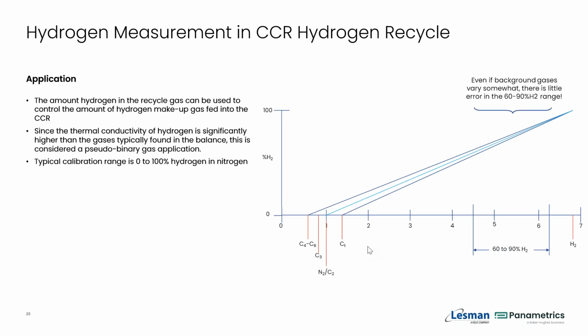In a CCR unit, there's hydrogen being fed in. There is your feedstock coming in, and then you have your product coming out. But in order for the reaction to go to completion, you do not typically use stoichiometric amounts of hydrogen. You don't try to do the chemical reaction one for one. You will always put in more hydrogen than needed to ensure that the reaction goes all the way. And then what you'll do is monitor the recycled gas for things like moisture.